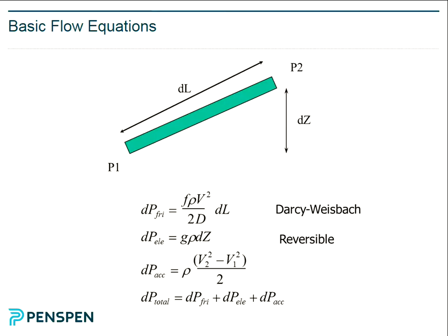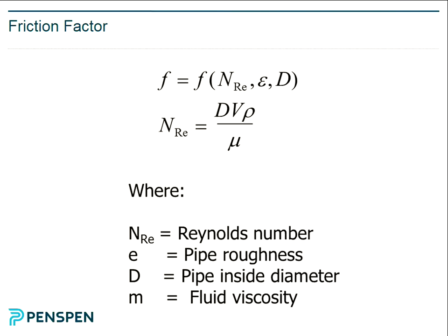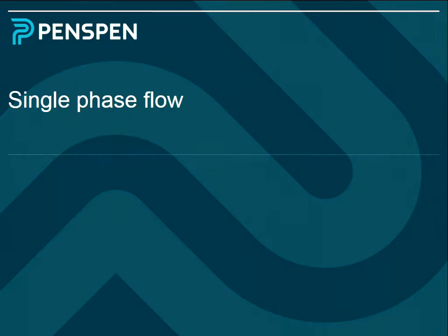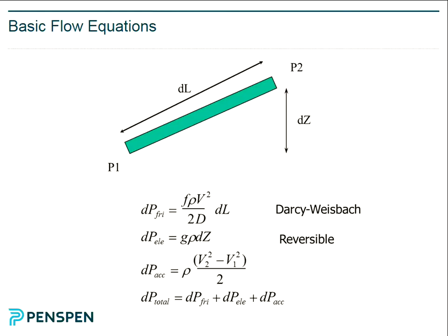You can see the friction factor F is on both sides of the equation. So if you want to solve this in a spreadsheet, which I was doing yesterday, coincidentally, you have to use an iterative technique. But it's fairly easy to do that. There are also a number of approximations for the friction factor for turbulent flows which you could use.